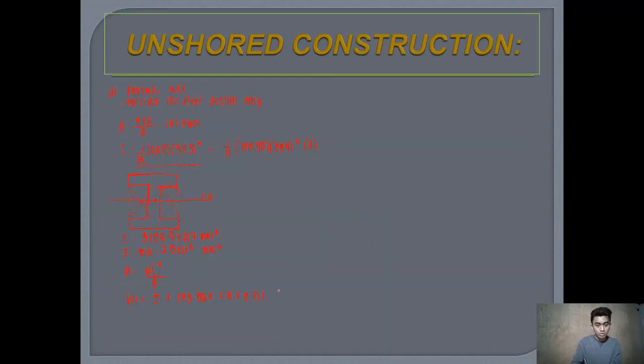But take note, that is 2 kPa, so what will I do? I will have to multiply it by the length now of the concrete, which is 1.2. Alright, so weight total now is equal to, considering the steel section only, 5 plus 23.56 times 1.2 times 0.1 plus 2 times 1.2 here.